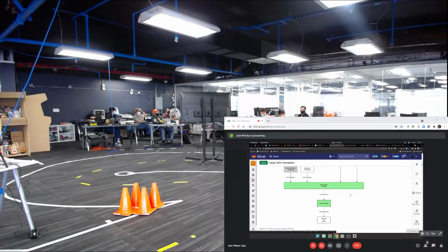And then those radars, is it 2D? Yeah, in this case, it's a 2D plane. So the active radars use an antenna array, and it has vertical segments. Each vertical segment can detect an object with a distance associated with it, but it can't do any vertical discrimination. So you get a chunk, and there's some object in that chunk, right? You can get a velocity and acceleration of that object, but you can't tell how high off the ground it is. You just know it's out there in that little space.